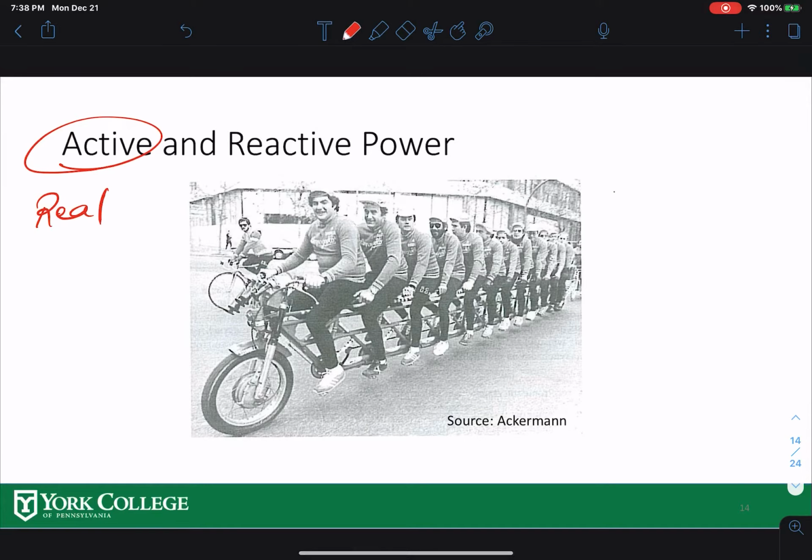You want your voltage profile to be straight. It's the voltage profile, right? But it can try to tilt this way, or I can try to tilt that way, so you have to balance it all the time. This tilting happens due to the reactive power in the line. It happens because of capacitors and inductors. Mainly in the line, you have inductors because of flux linkage, and you have capacitance because of the electric field. There's a voltage difference between the lines. So those things try to push your voltage one way over the other, and the other needs to balance.